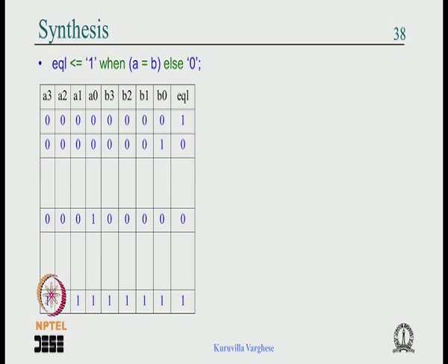So maybe I am exaggerating, but you see that a very simple solution doesn't work here, it uses a lot of memory, and because of the exponential complexity of the digital case with the minterms, it goes exponentially complex. So most synthesis tools don't build truth tables.